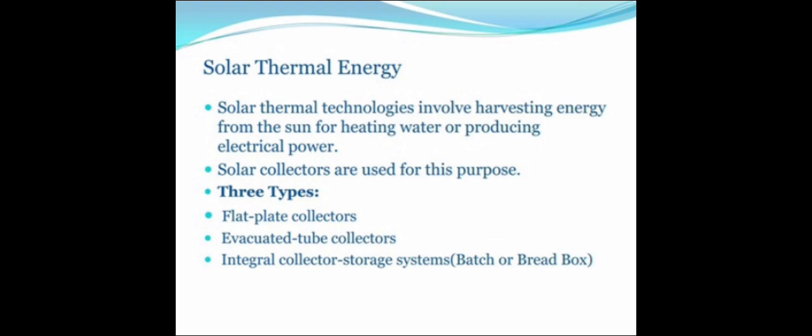Here we are going to discuss three types of collectors. Those are flat plate collectors, evacuated tube collectors, and integral collector storage systems. The first one is flat plate collectors. Flat plate solar collectors are probably the most fundamental and most studied technology for solar powered domestic hot water systems. The basic principle of this device is that the sun heats a dark flat surface which collects as much energy as possible, and then the energy is transferred to water, air or another fluid for further use.